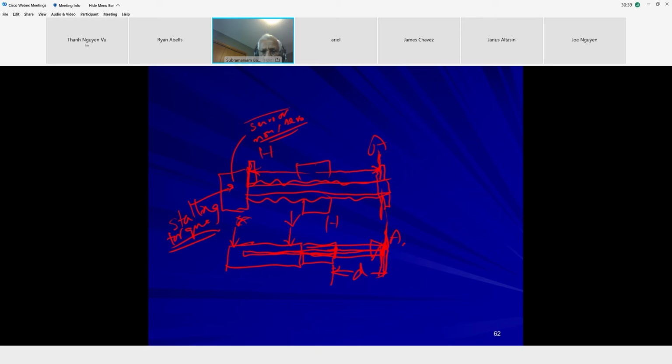That's about it, through a solenoid valve. There is no other electricity going in. So this also becomes a non-servo application. In robotics, this is very extensively used. There are cases in point-to-point applications where you don't care about intermediate positions. Plus, there is no path control. In this case, it's all straight line.